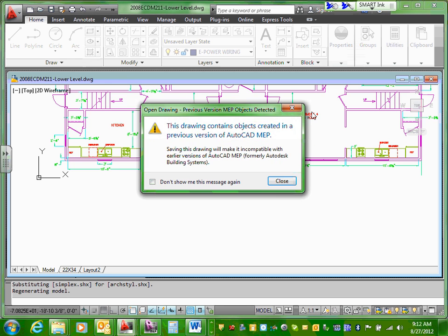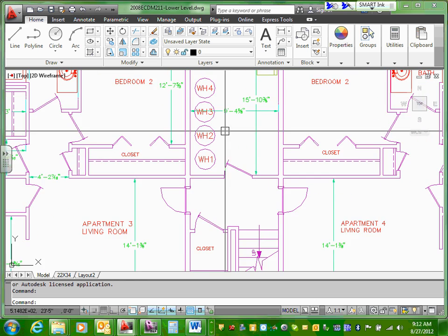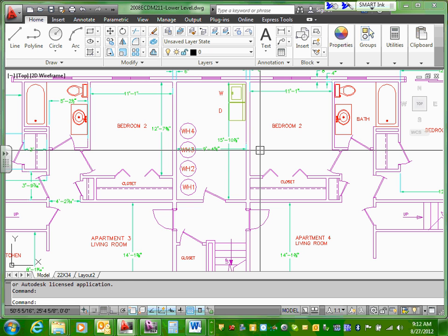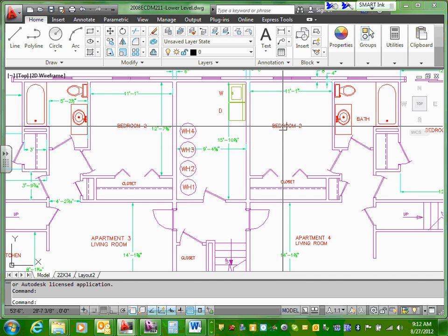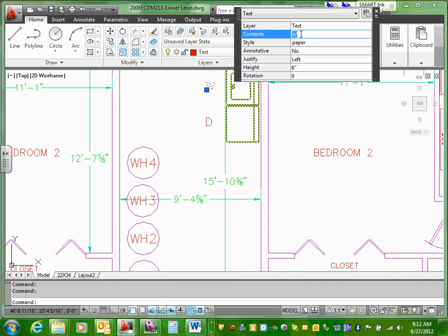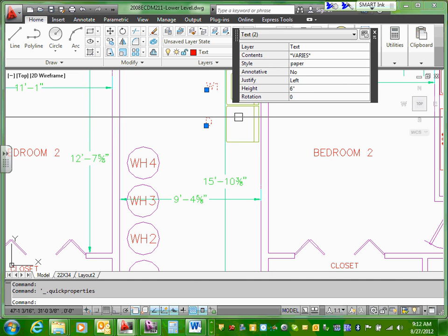Okay. Now guess what I have? Now I have a file that actually has a background. The background itself. I opened the background itself. Okay. Are you guys looking at what I'm looking at? Okay. Now the first thing I would like to do, guys, is, do you see where it says dryer here? A dryer D1. You click on it. Why don't you guys put washing machine 1, and close it. And right here, double click. It opens the text for you.